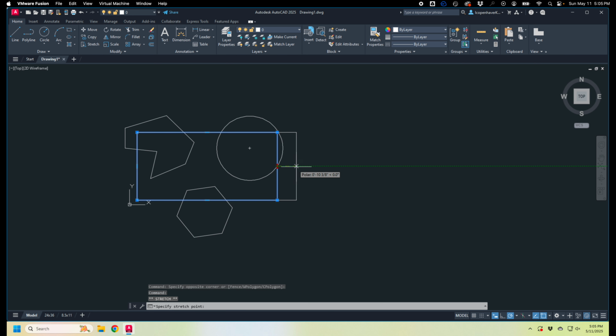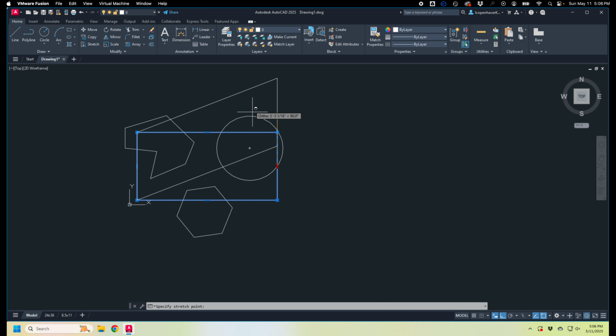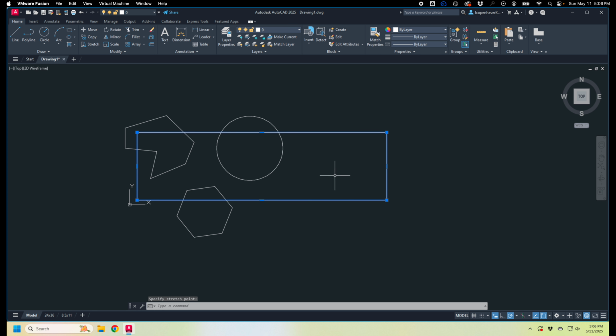How they behave is consistent across shapes. One thing to note is that if you push, you can change what the shapes are doing. So there's a bunch of options here, and if you hold shift, it locks you into a 90 degree, which is to a point. Oh goodness, to a point. Once you're out here, it locks you into 90 degrees. Which can be helpful for some two-dimensional drafting stuff. Again, it's one of those places where a lot of times we just don't need that functionality, but it's a good thing to know about. What we do use quite often is the move command.